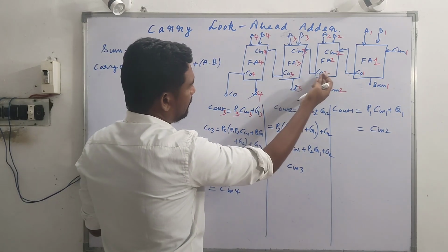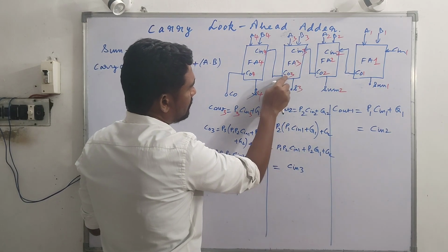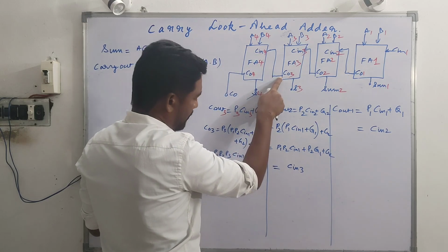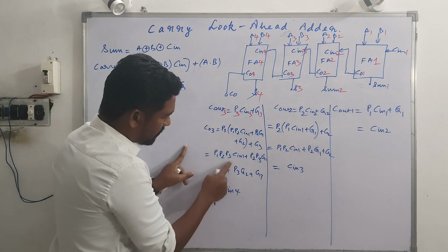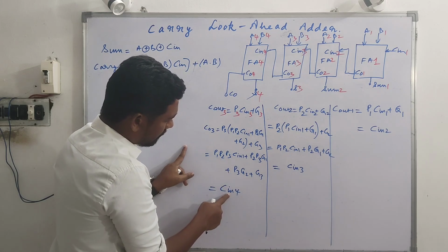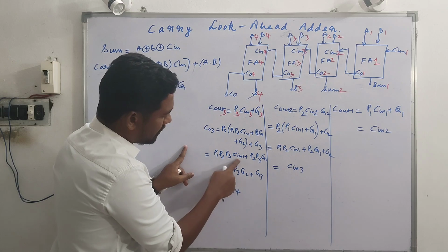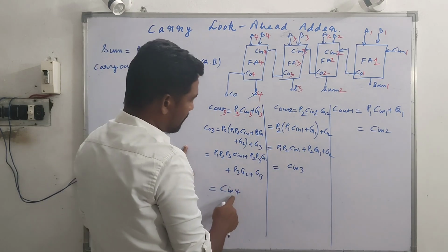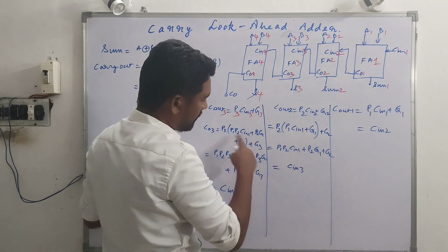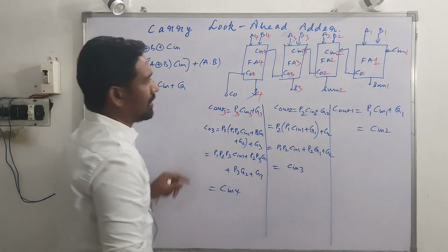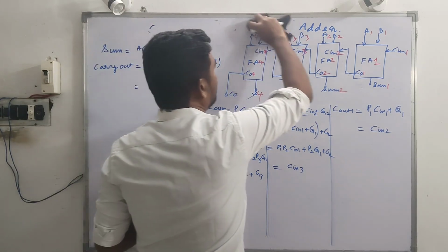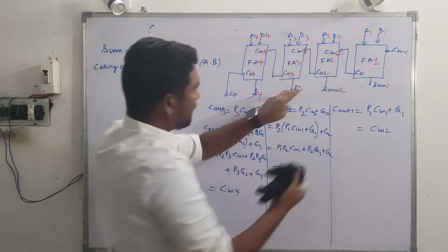And from the parallel adder, once again, C in 4 depends upon C out 3, whereas from this Boolean expression, C in 4 simply can be produced at the same time C in 1 is given. This C in 4 does not need to wait for C out 3. This arrangement says, guys, that the carry look ahead adder isn't something different, but a modification of the parallel adder.